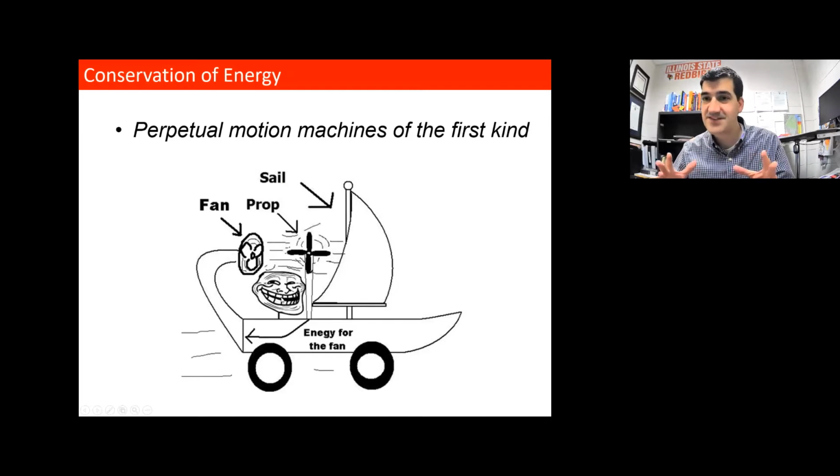So the only way this has any chance at all is if both the fan and the wind turbine are 100% efficient, which we know they cannot be. But even if they are, then all of the energy from the fan has to go into wind that will go to the wind turbine, right? And the wind turbine has to use that energy. So there isn't anything left over to push on the sail and power this car.